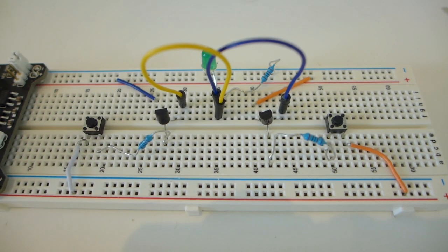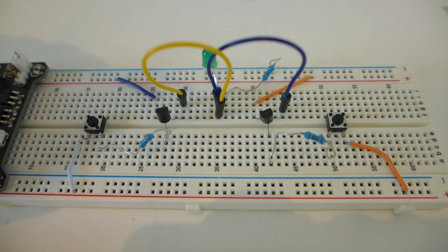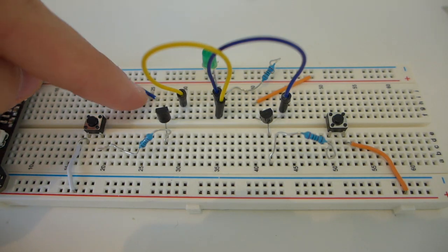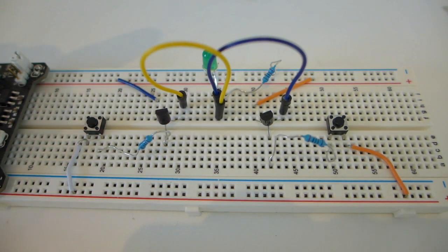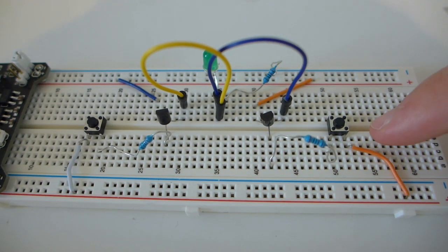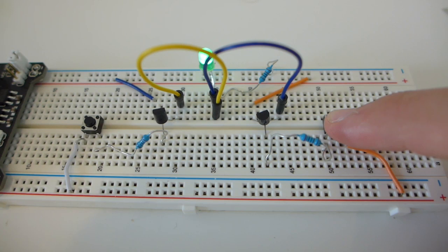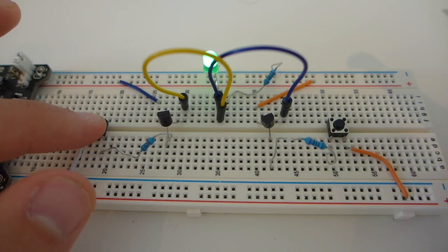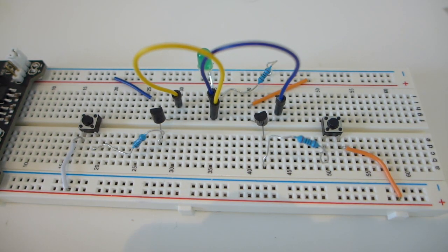And here's our OR gate in metal. Each input is wired through a button to the base. Each transistor is wired separately, and then the current from each emitter converges on this green LED here, which is the output. Now by pressing either button, taking either or both inputs high, we see a high output. And that is our OR gate.